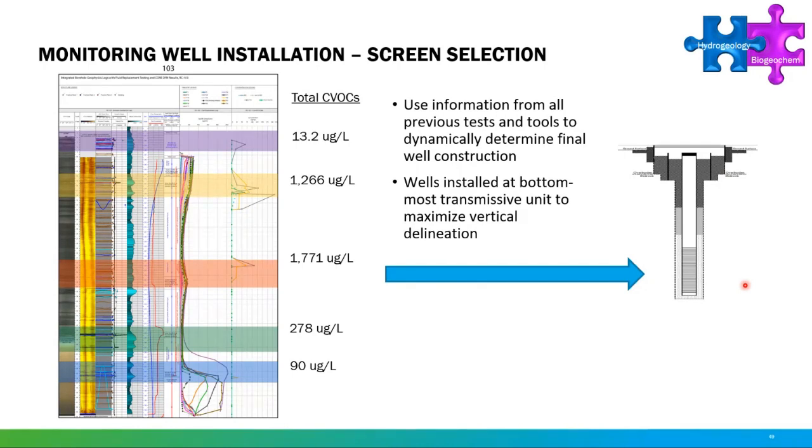So in this case, we look at concentrations and we look at the purpose of this very specific well. One borehole may have a different purpose than another borehole. In some cases, we might be trying to delineate below the plume, delineate vertically, so coming in underneath the plume and having low concentrations there. In other cases, we might be trying to delineate beyond the highest flow zone, beyond the highest HSU, or in other cases, we may be trying to delineate side gradient.